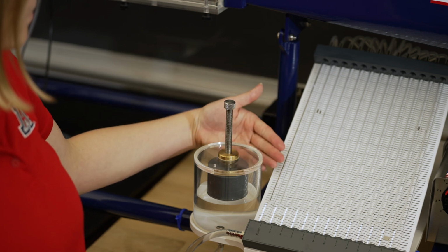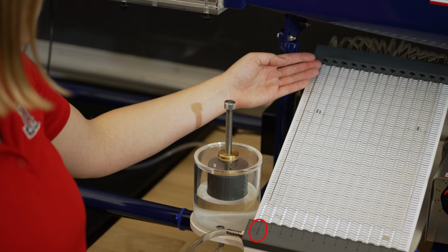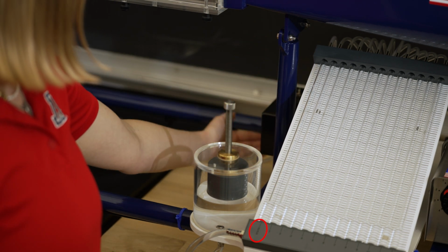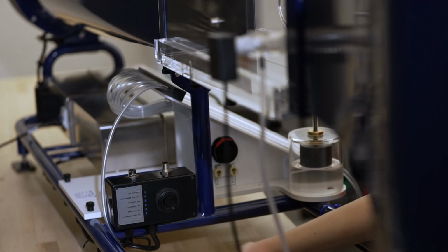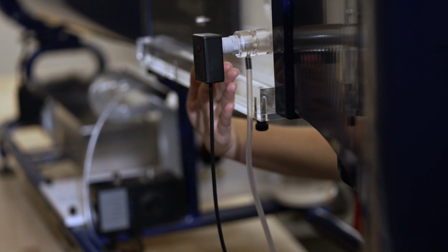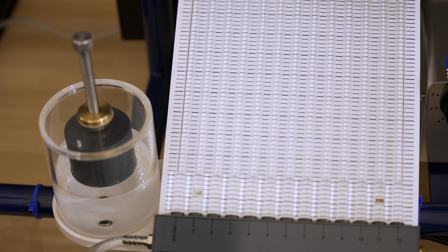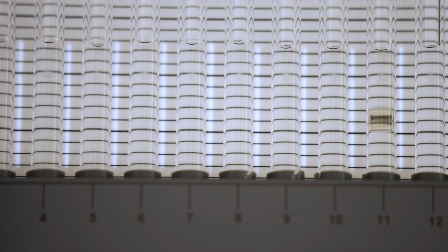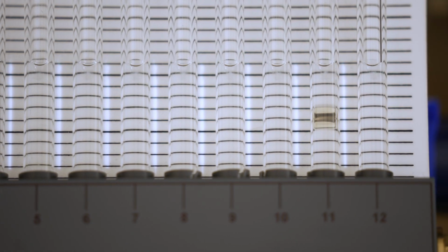The manometer has 12 tubes. The first one correlates to the static pressure measured by the static sensor located on the back of the test region. The static tube is connected to the pressure sensor through this clear hose. The 11th and 12th tubes are open to the atmosphere and indicate the atmospheric pressure. The other tubes can be connected to measurement instruments and models. The student can read the wind tunnel manual for more details.